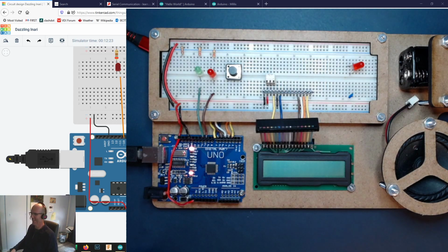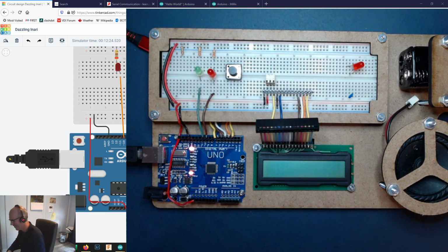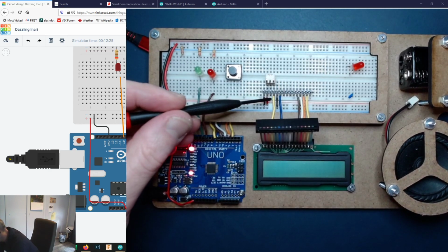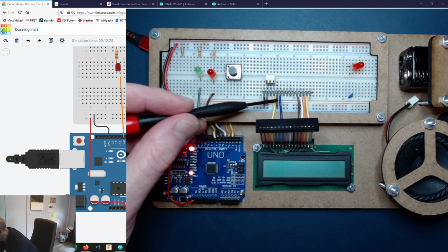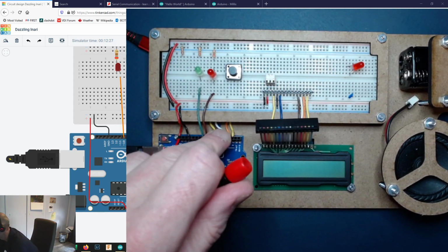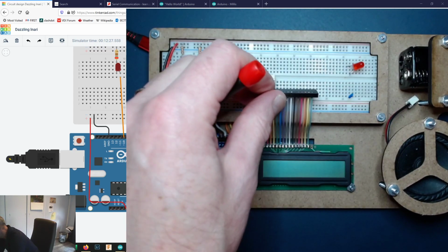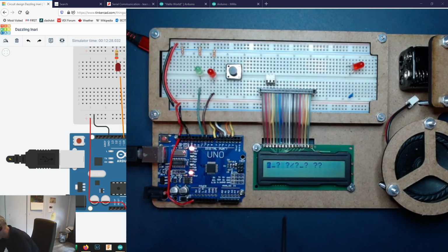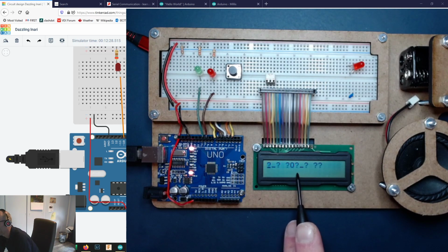So anyway, as I was saying, I made a mistake because I had this yellow and I thought I corrected it by moving it over here, but it was in the right pin. Aside from that, I went through and re-wiggled all these pins to make sure they were in nice and tight. And now when I put this together, well, I just plugged that on there and I'm getting weird characters popping up here, which is a really good sign. If you're getting weird characters, that means you have communication.